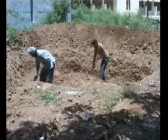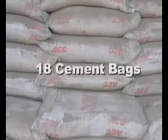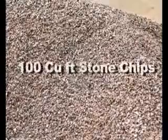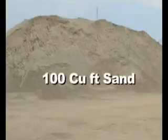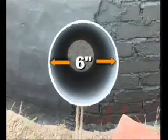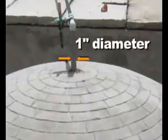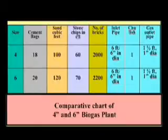For the construction of a 4 cubic meter capacity biogas plant, the materials required are 2000 bricks, 18 bags of cement, 100 cubic feet stone chips, 100 cubic feet sand, a 6 feet long pipe having 6-inch diameter and a 1.5 feet gas outlet pipe of 1-inch diameter. Similarly, for constructing a 6 cubic meter biogas plant, we require some extra material as shown in the table.